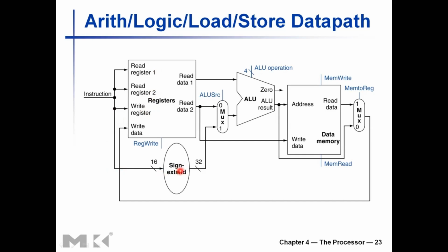into the sign extender. So we get the sign extended immediate value here, but that immediate value doesn't make any sense because the instruction did not have an immediate value. The number coming as an output from the sign extender in that case does not make any sense. So it goes into the multiplexer's input, but we should only take the register file's output as an input into the multiplexer. So the multiplexer select signal should carefully only take that and send that to the ALU, right? You will get some input here into the multiplexer, but that is not a meaningful input for R-type instructions.